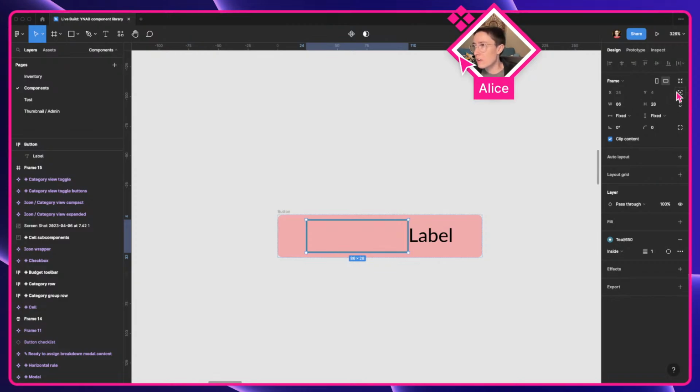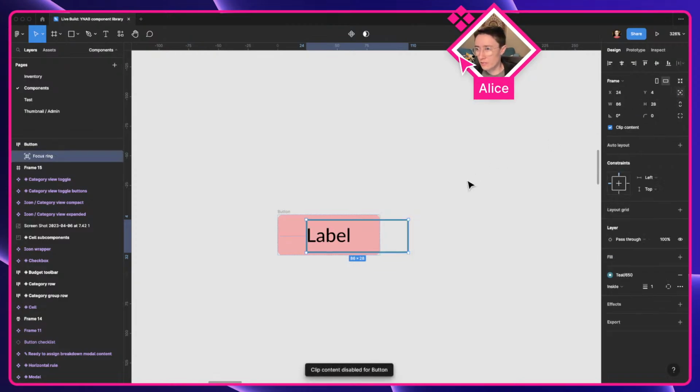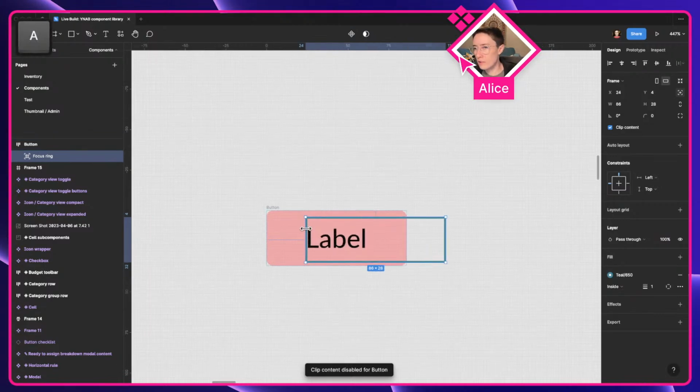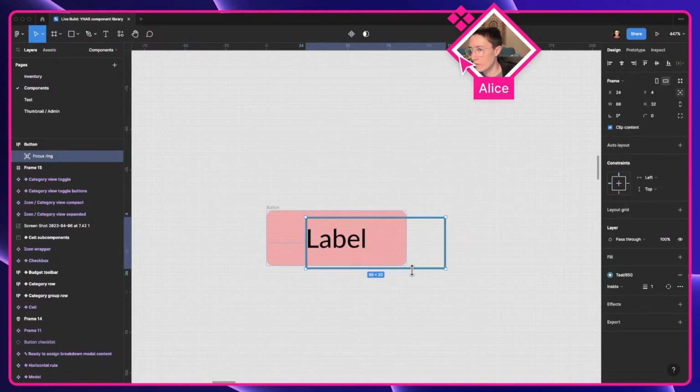The whole trick is absolute positioning. That's what allows us to do this. So when we absolute position that object, now we have the freedom to place it anywhere we want and use constraints to make sure it's aware of its parent's dimensions, and then stretch or squash to whatever we tell it to.